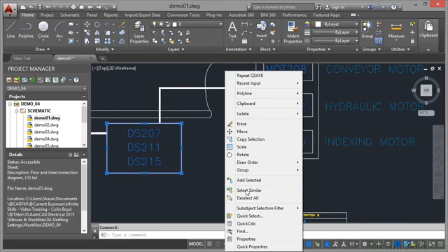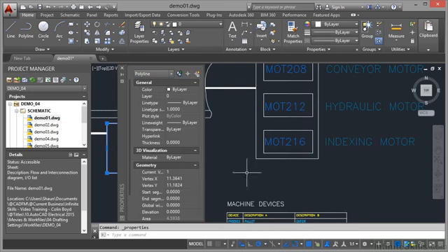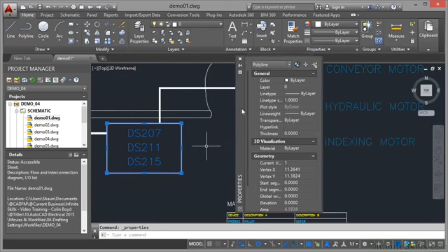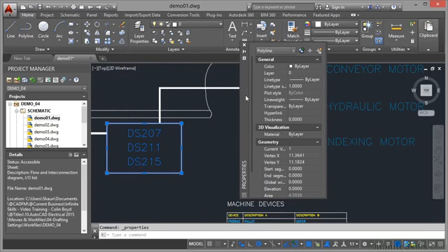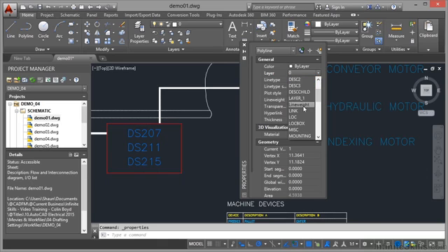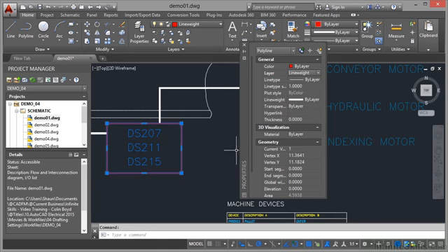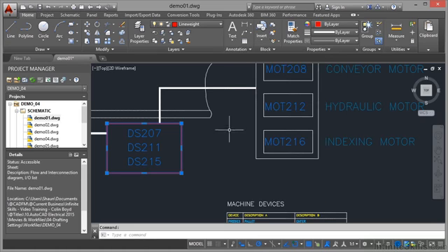Now right down at the bottom of that shortcut menu is Properties, so I click there, and that'll bring up the Properties palette. That's obviously obscuring the rectangle, so I'll just click and drag on the title bar like so. You can see there, it's telling me it's on layer 0. So if I click there, click on the flyout menu, and if I come down now, there's that line weight layer that I set up. Click there, and now I close the Properties palette, and then I just hit Escape. And as you can see there, that has obviously changed the properties of that rectangle.